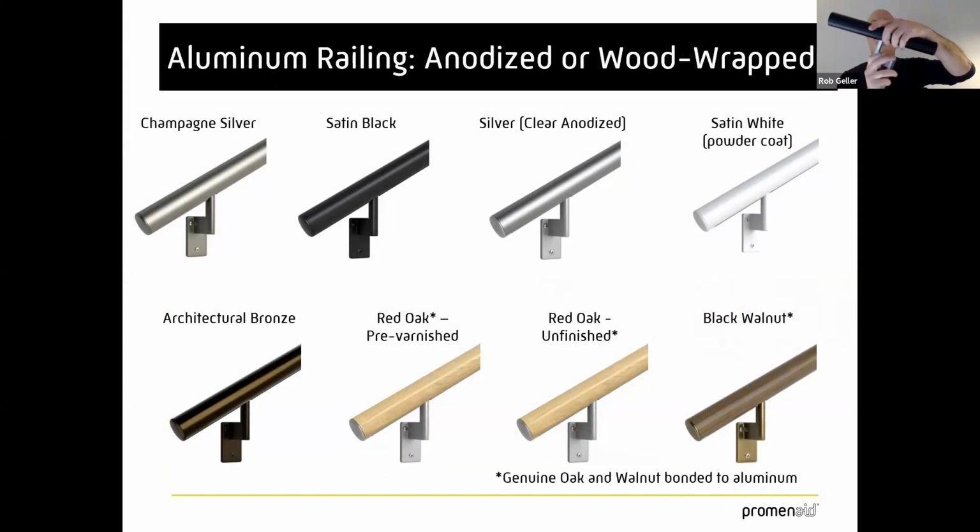You can put the bracket in anywhere you want. You lock it in place, that's it. And then you pivot the railing to whatever slope you need or horizontally. Each one of these brackets will hold 500 pounds, cumulatively. So at minimum, get two brackets into the studs, and you've got 1,000 pounds of support.